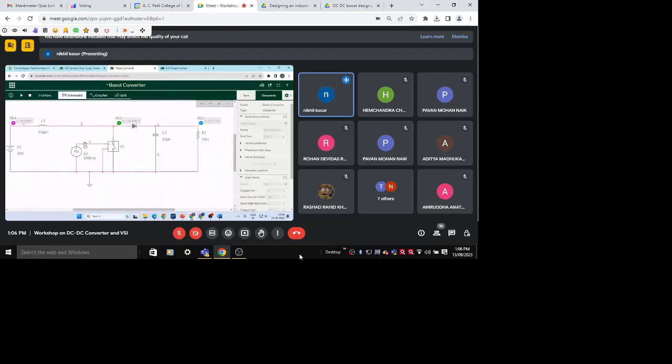Now this required frequency cycle needs to be generated using a digital or analog circuit. Analog circuit means you have to use an astable multivibrator using IC 555, and whatever you have studied in the syllabus or subject, maybe analog electronics. In that you have studied the multivibrator, but with constant, fixed duty cycle. Here we want variable duty cycle in DC to DC.